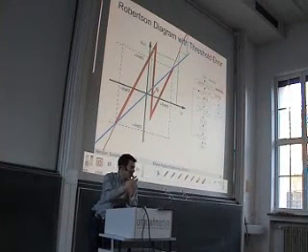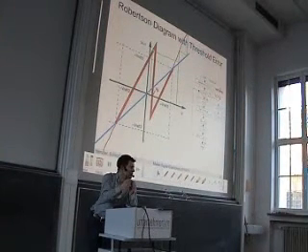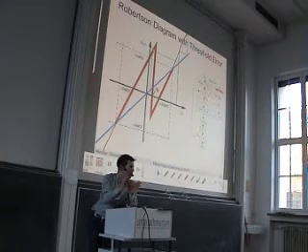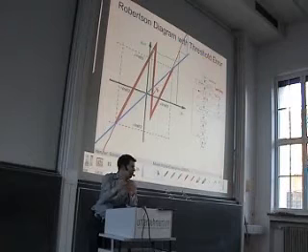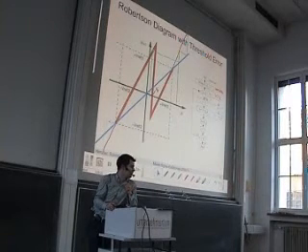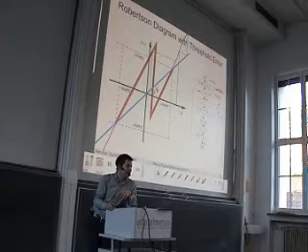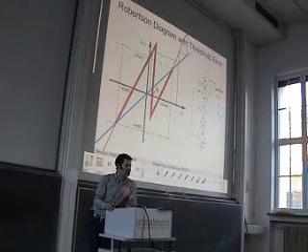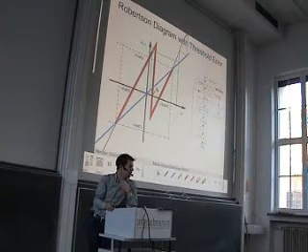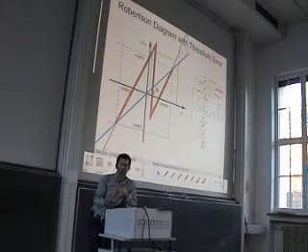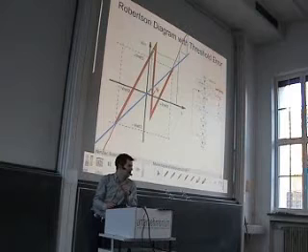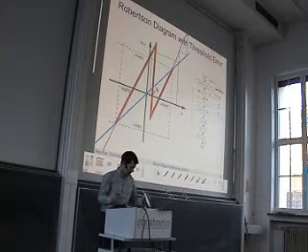So it is not avoidable that you fall in this region, maybe it is small, but it is there. But if you fall in this region, then your algorithm does not converge anymore. So somehow this ADC conversion algorithm is not robust against variations, because each variation in the threshold may lead to an error.